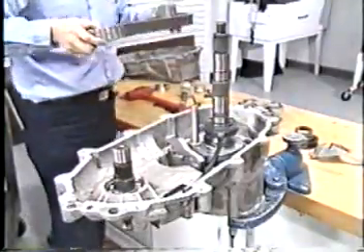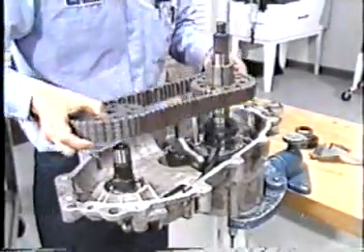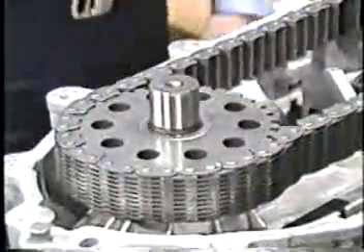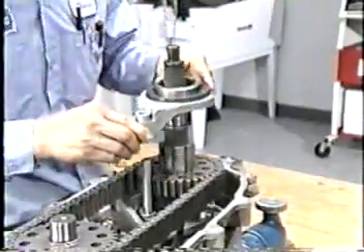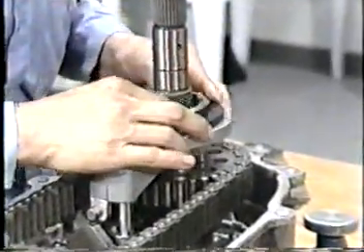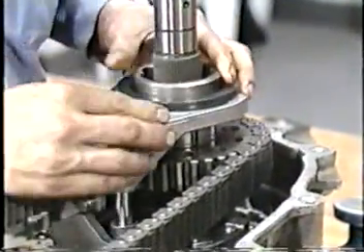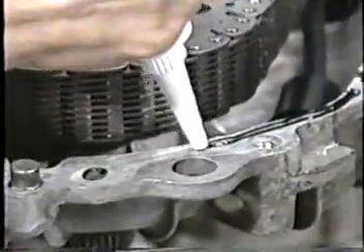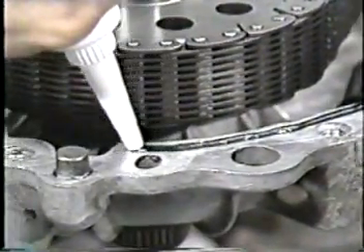After installing the front output shaft through the lower bearing, install the sprockets and chain. Followed by the two-wheel, four-wheel drive lockup assembly. Be sure the orientation is correct because it can be installed backwards. Apply a bead of silicone rubber to the front case and install the rear cover.